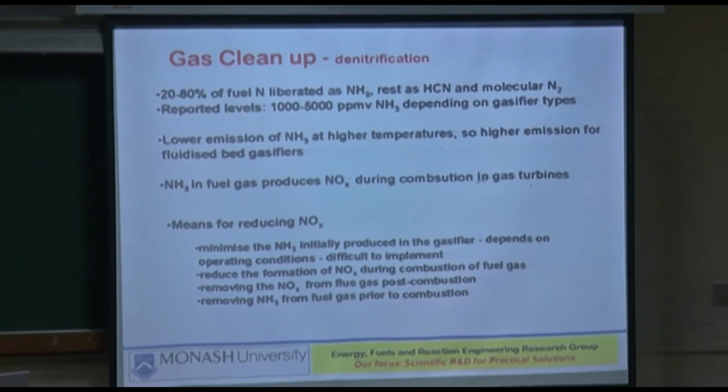In a combustor, you don't get ammonia because you have oxygen, so ammonia is oxidized to NOx, and that's another set of problems. Right? Whatever is in the coal. But its effect is not to be underestimated, because in any gasification work, even in your pyrolysis work, if you just try to detect ammonia, you'll find lots of it. And biomass has a lot of nitrogen in it, so you can even consider selling ammonia if you want to.